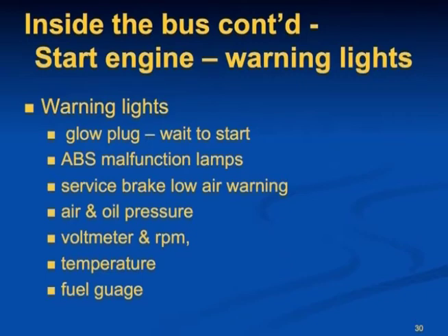Oil pressure warning lights may go on as the bus is being started, but it should go off after the engine starts. If it does not, the engine should be turned off and reported to a mechanic immediately. The alternator warning light: if this light remains on after the engine is running, it indicates a malfunction in the charging system. Report the condition at once.